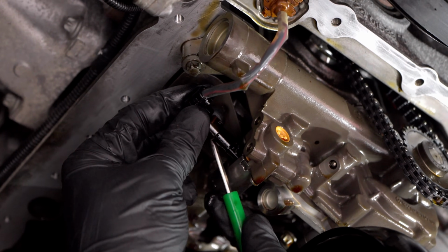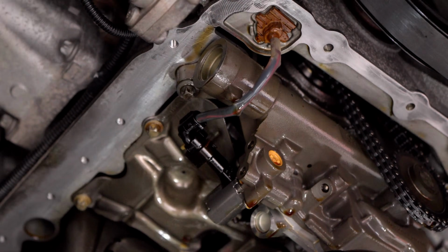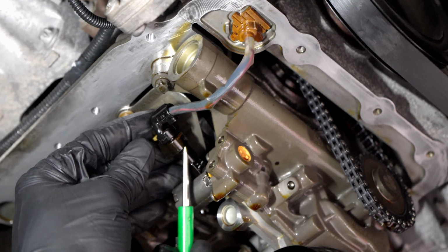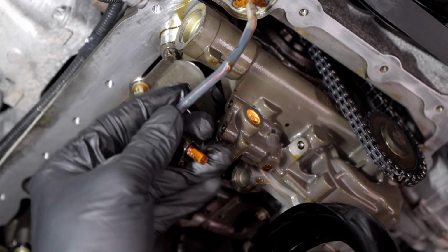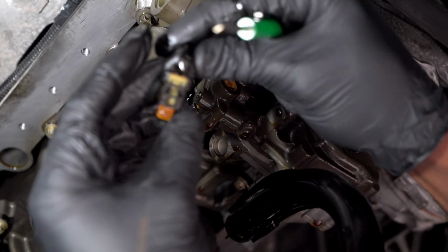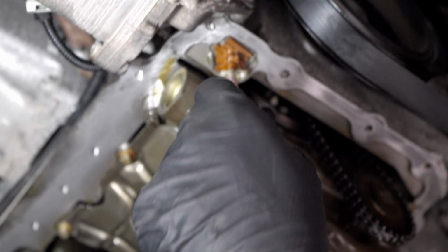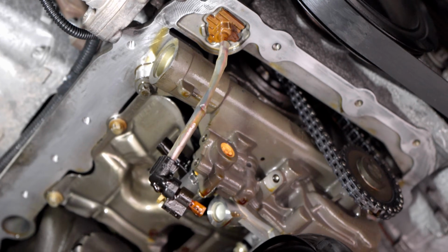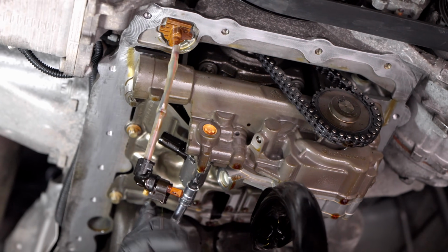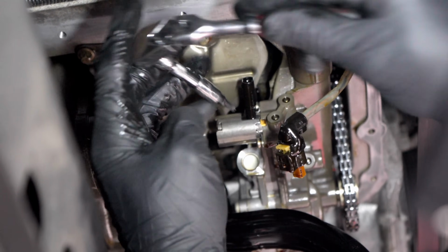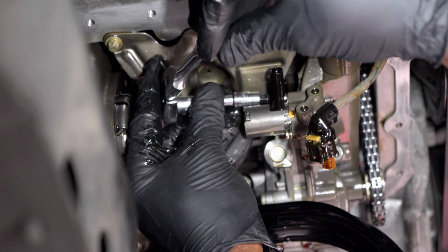So I'm gonna disconnect. Should I put the light on this side? Is that better? Okay, so we're gonna remove the solenoid first. So what usually happens is this wiring gets brittle. So we're gonna change this little wiring harness. So I'm gonna remove the solenoid first. So the screws that hold the solenoid in place are T20 screws. And then there's another screw up here.